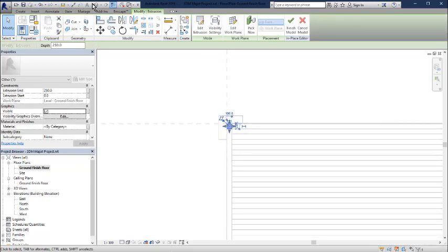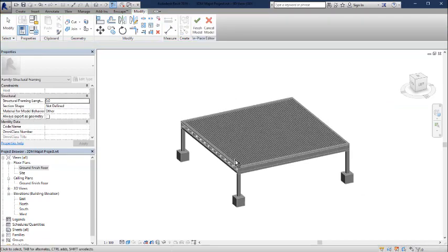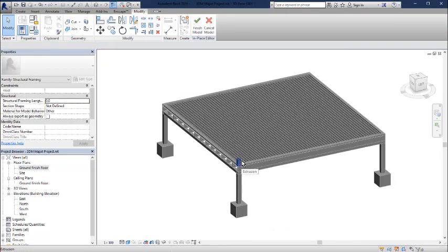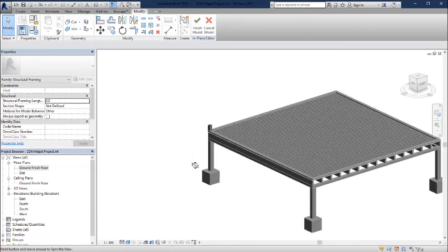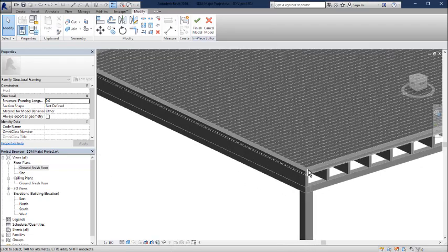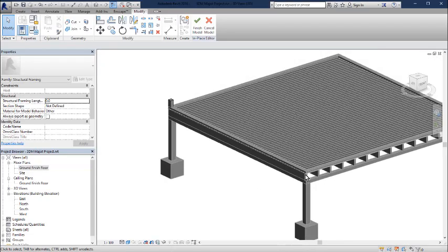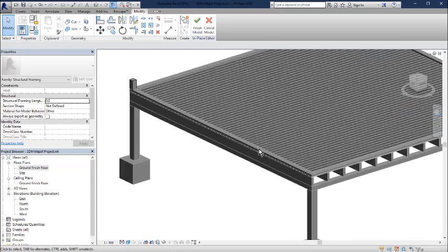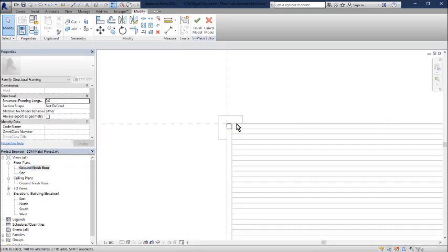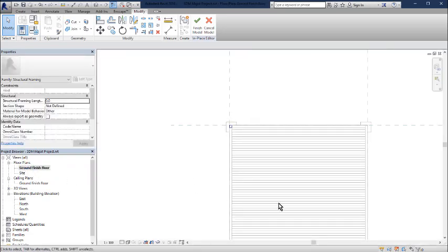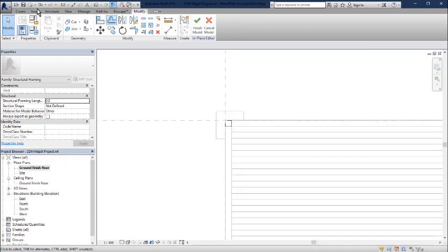So if I look in 3D view, that's actually my stud here. Now my balcony is going to be on this side. So my stud is actually going to stop from about right here, right? And what you can do is on your ground floor, we can lay out some reference points so that we know where everything goes, right?